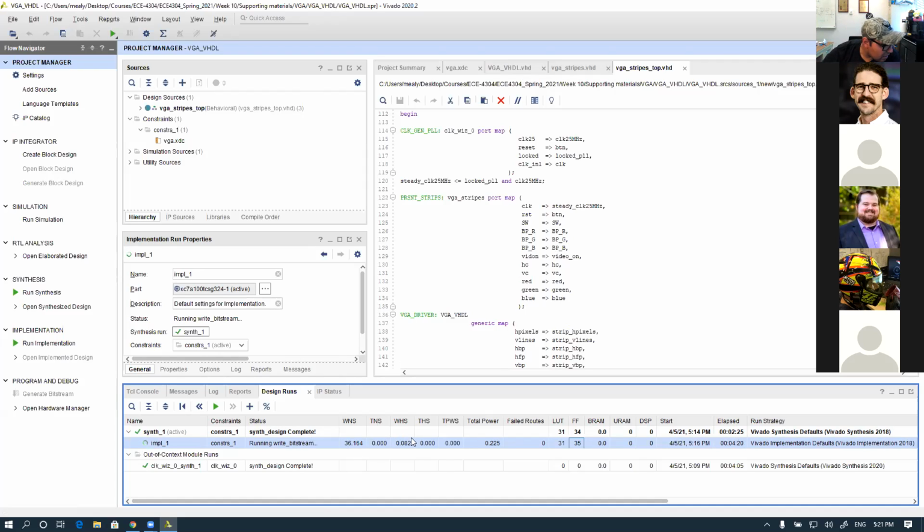Did you see that? The timing never came out negative, which is a good sign. All of the timing values here, WNS, TNS, WHS, THS, TPWS, two of them are associated with the setup time, two of them with the hold time. And nothing is negative. That's a very good impression. Everything is perfect. If it's negative, then we have to redesign something or lower the maximum frequency to meet the timing, so there will not be metastability issues. Okay, doke.